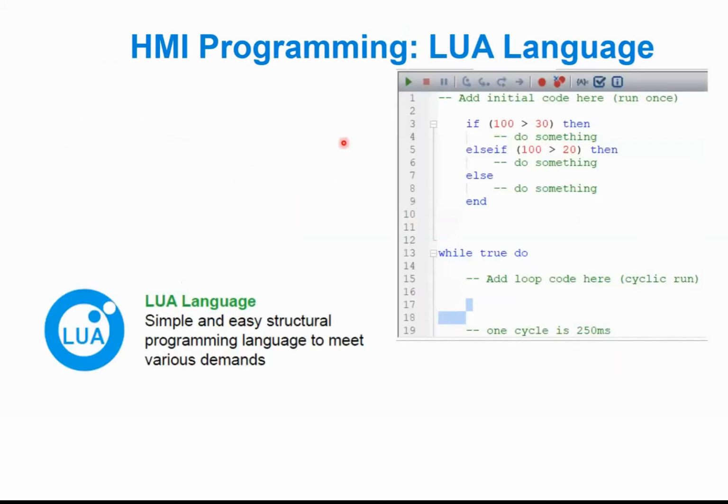The third and last way you can program our HMI is through ladder language programming. It's quite similar to the macro, the difference is that you write it in a different area. There's an area we create on the HMI where you can write your ladder code instructions. This programming type is just based on instruction. Based on the instructions you have written, the HMI will control your application.